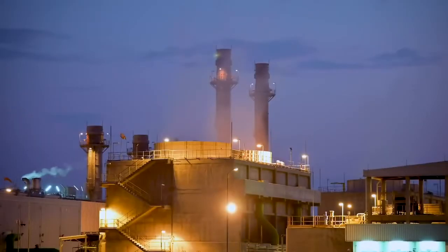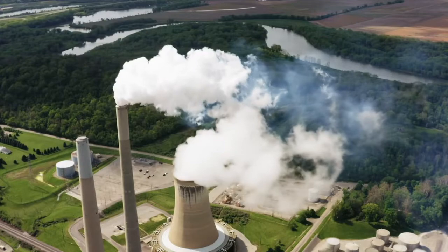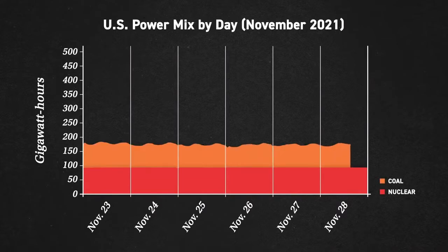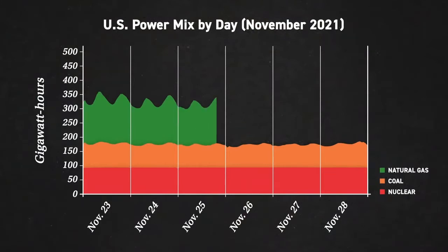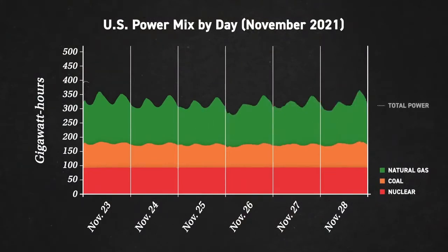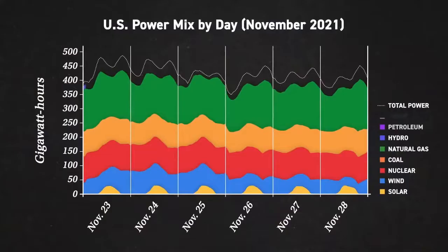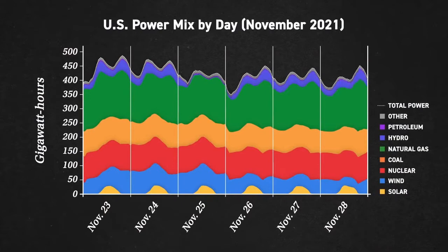Certain kinds of power plants, such as coal and nuclear power plants for example, have limited short-term flexibility in modifying their energy production. Ramping up or down their electricity output takes a lengthy period. Other facilities, such as natural gas-fired plants, can be swiftly scaled up and are often utilized to satisfy demand spikes. There is always a reserve margin, a certain amount of backup energy producing capacity available to compensate for forecasting mistakes or unexpected power plant shutdowns at any given moment.